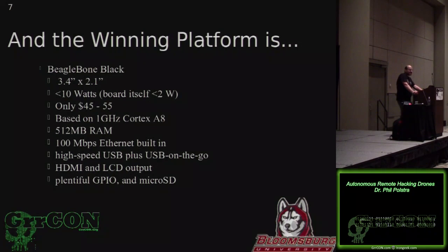Originally, I started this work, some of you might know, on the BeagleBoard XM, and then the BeagleBone Black came out, and it was about the same power, a third of the price, so I kind of went with that. They're pretty cheap. They have enough memory, and most importantly, they don't use a lot of power. The board itself uses less than 2 watts. You can have a whole system for about 10 watts. Lots of GPIO if you need it. Just a fun little board to play with.